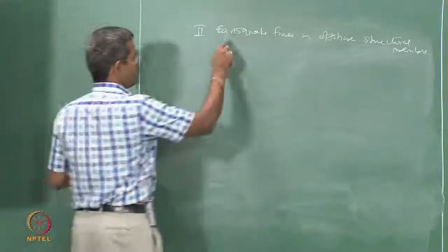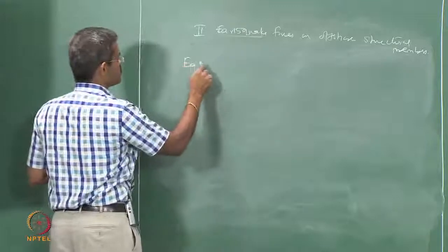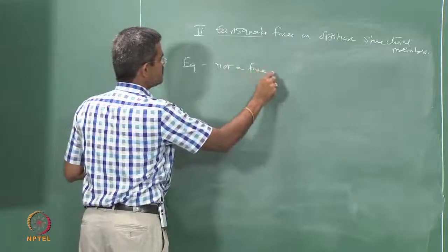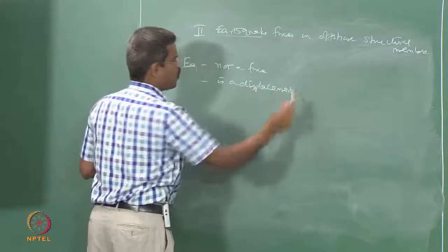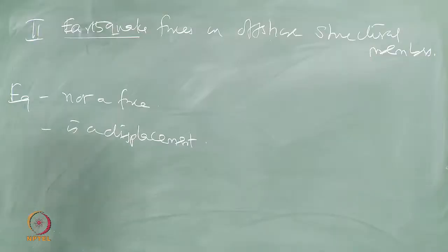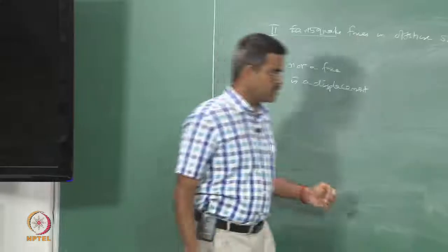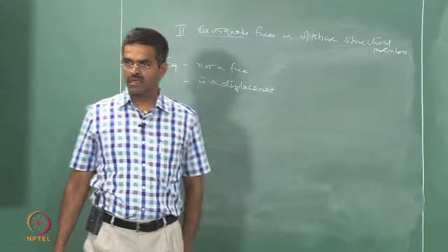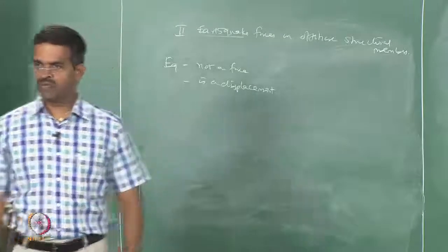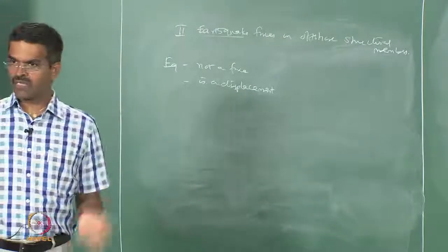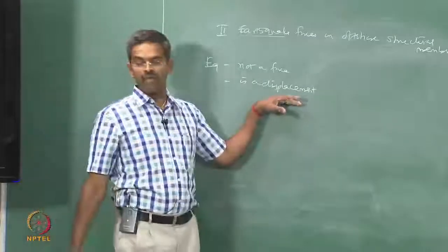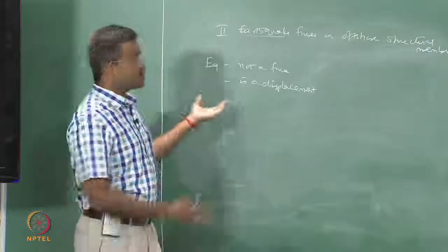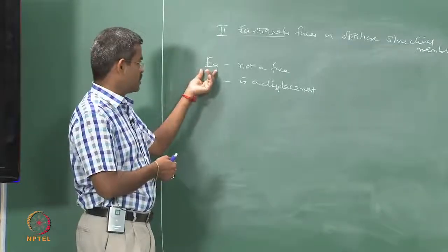Similarly here in earthquakes also, earthquake actually is not a force, actually it is a displacement which causes the force. Now we are very clear about this idea how displacement can cause a force. Just now we saw in Morrison equation, when the water particle displaces it generates velocity and acceleration, when the cylinder interferes the flow field it generates force on the member, and the cylinder is also vibrating, it will give a secondary force which we say radiation etc. In the last lectures we know how the displacement can give rise to a force in a fluid medium. Same concept in earthquake. Now earthquake gives forces through its displacement.